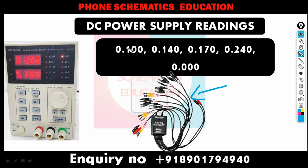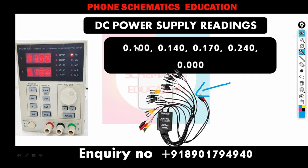Also keep in mind, one thing: the boot cable also plays a major role in diagnosis. Suppose a phone comes to you with a low battery, and you see this reading. According to the reading, you can work on your CPU and find the short in a secondary line.